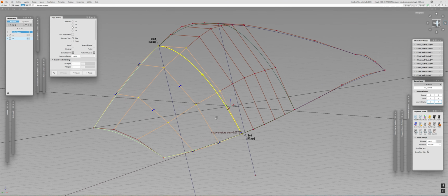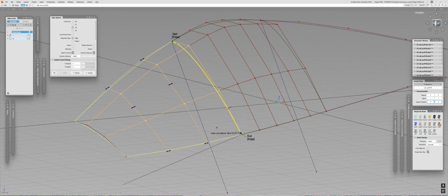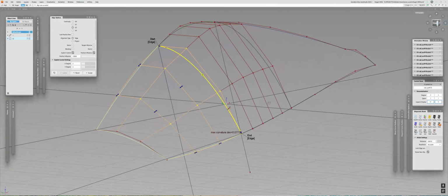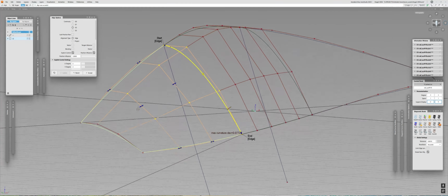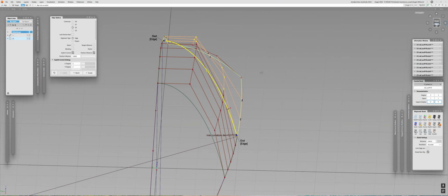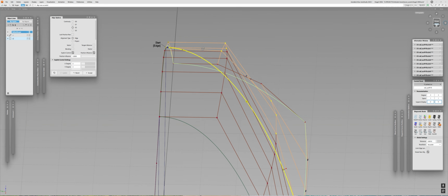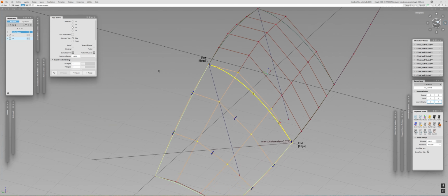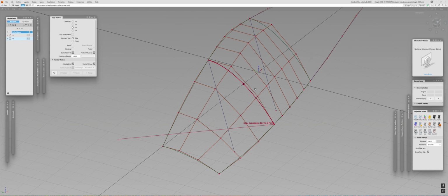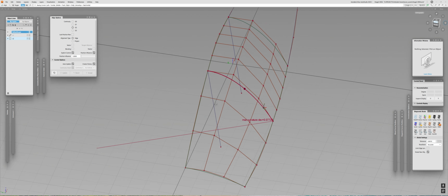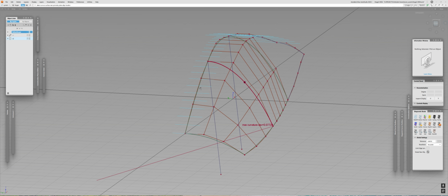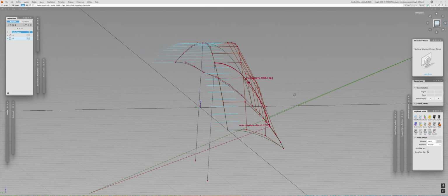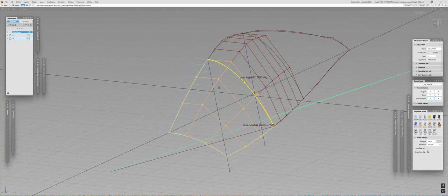All right, now as you're gonna see, I have the curvature deviation of 0.07, quite a small one, but I'm working with tight tolerances, so for me it is an issue and I need to tweak it. But apart from that, if you look closer, we are lacking continuity across the center line. So before I fix any of this, I actually need to work on the alignment across the center line. So let me click on that again, delete the history, and now it's properly aligned across the center line.